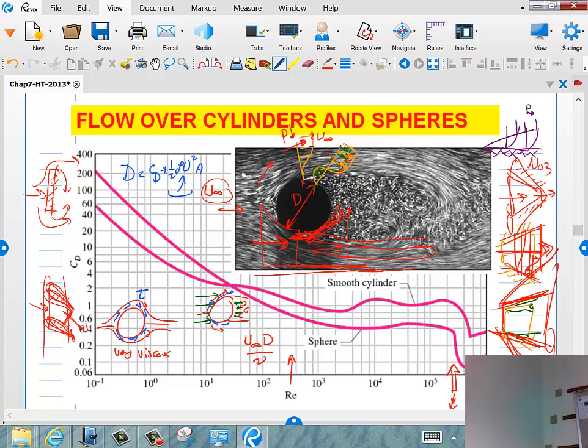But once you open it here, now he has a choice. He can either follow you and make his pressure go up, or if this area is really, really big, he will say, I'm not going this way, I'm just going straight. I will separate from the wall because you are asking me to increase my pressure really big. Right? And it's that difficulty in building the compressor. That's why the jet engine was invented on paper for a very long time, but they couldn't really make it work until the Second World War, when they managed to make it work on the compressor side. Right? Because it's very hard to make the air go without separation.